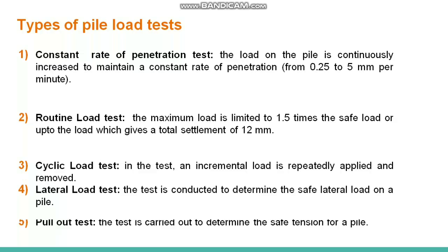Pull-out test. You have seen a tension pile or anchor pile. That pile resists tension load. For that kind of pile, we determine the capacity by using the pull-out test. In this pull-out test, we apply a tension load on the pile, and then we see all these criteria.